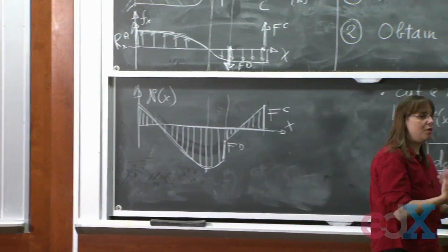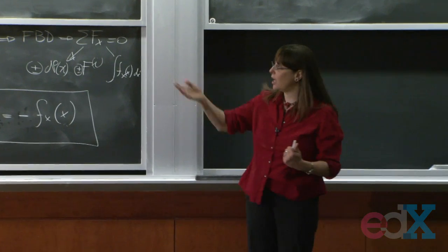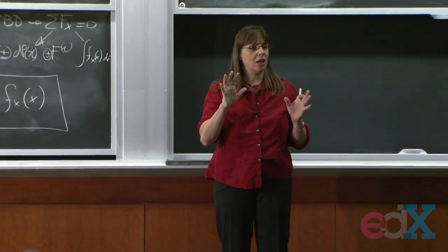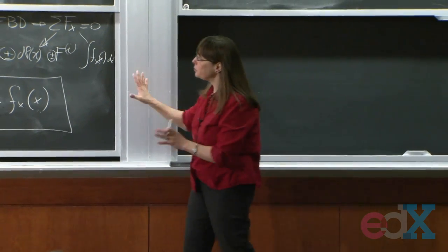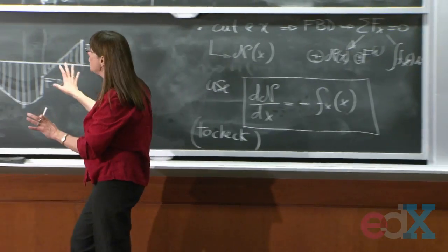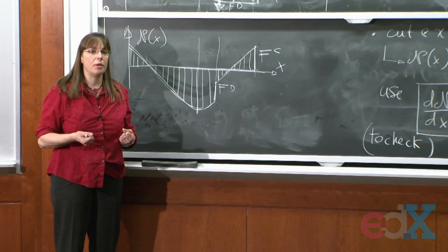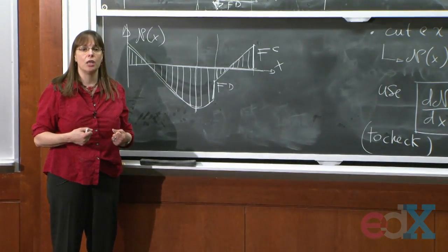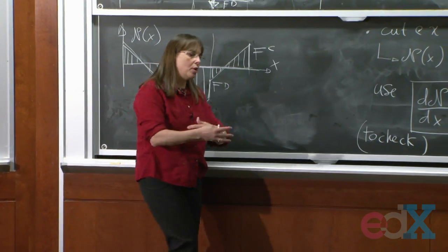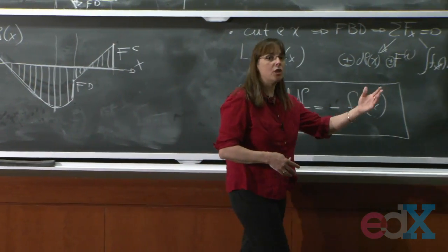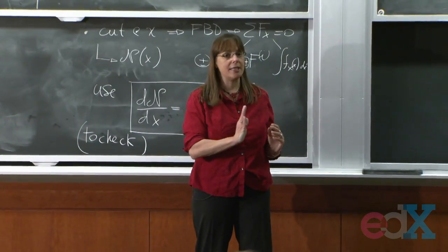So I do not know if this helps you. It helps me sometimes if I want to do something quick to see if the diagram of N of x makes sense, if I have a confusing force loading. It helps me to get an idea of what the sketch should look like. It's a good idea if you start thinking in these terms, because this way of thinking is going to help you a lot when we do beam bending. Because in beam bending, typically you may have distributed load, you may have concentrated loads, and we're going to use a similar trick to kind of get a sense of what happens inside the beam.